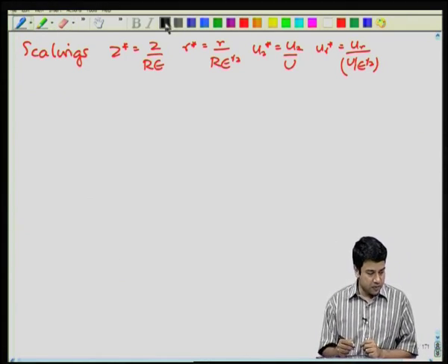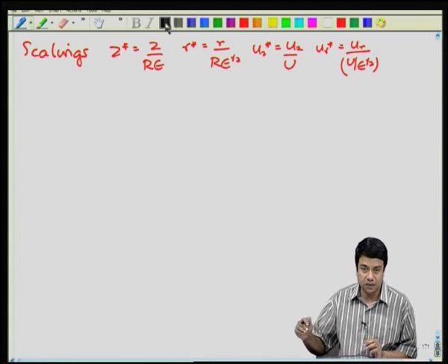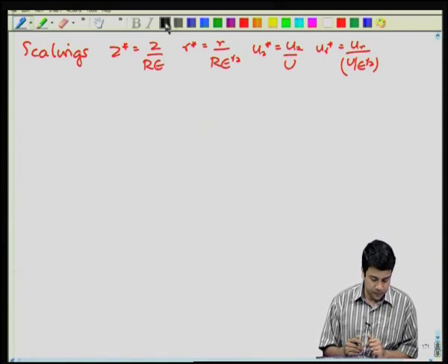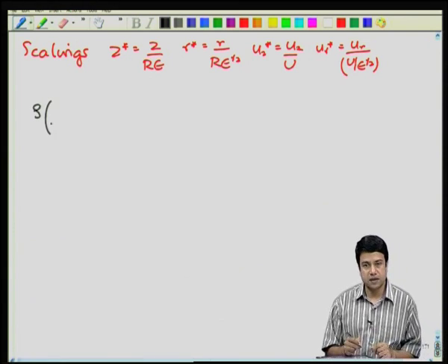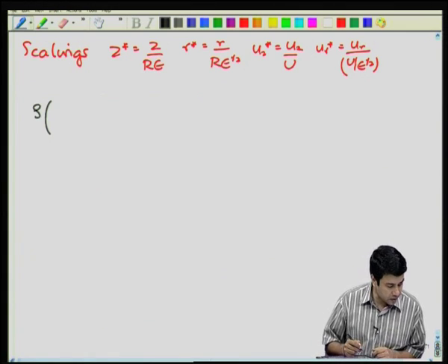Momentum conservation equation, the radial direction, I will take that first, because I would expect the momentum conservation equation in the radial direction to generate the pressure force required to push the fluid through. Okay. Physically, that is the reason. So, the momentum conservation equation in the radial direction, axisymmetric. And for the moment, well, I can include the time dependent term as well.